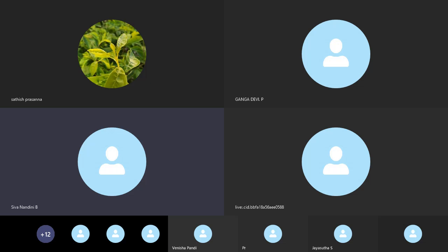So there are numerous diodes, capacitors, transistors. To have a unique name for each and every diode, capacitor, resistor, we are giving a reference designator. For resistors, like we saw in the previous case, R1, R2, like that we'll be giving reference designators. For transistors, we'll be giving T1, T2, likewise. It is our wish, we can give any name as reference designator, but it should be a unique name given for that component. Next, go to slide number 11.